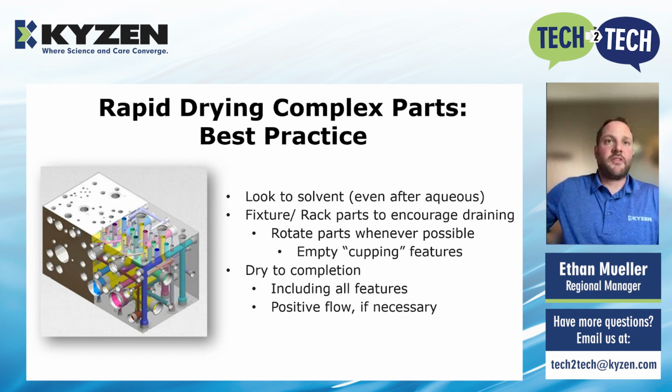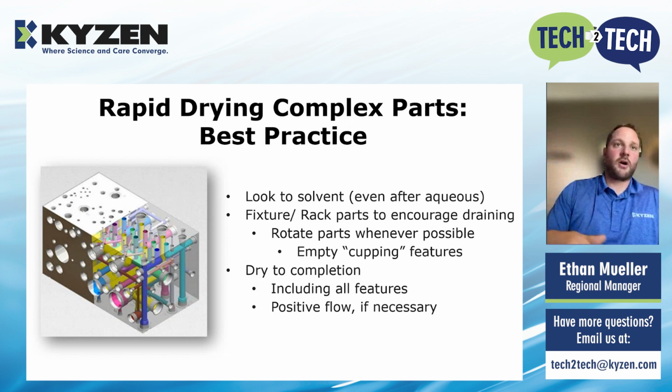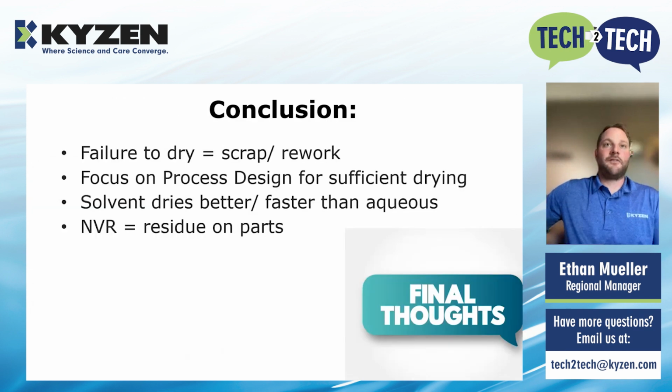Something that you can do is use positive flow, which is basically directing air or something through the intricacies of the part to aid in getting that solution out of those complex features. In conclusion, failure to dry ultimately is likely going to lead to scrap or the need to rework a part. Obviously, that's undesirable, costs money, takes time, reduces our throughput, upsets our customers.